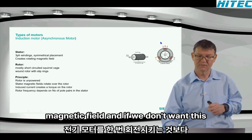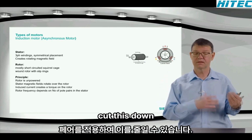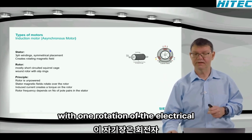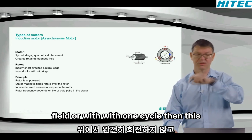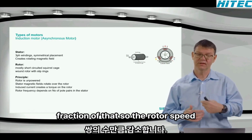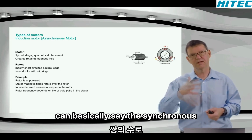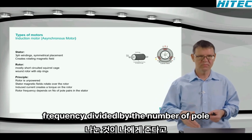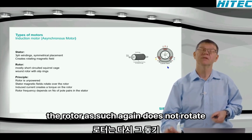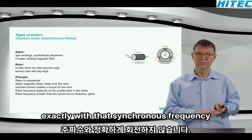And if we don't want this high speed, we can cut this down by applying more pole pairs. Then with one cycle of the electrical field, this magnetic field does not rotate completely over the rotor, but only a fraction of that. So the rotor speed decreases by the number of pole pairs. We can basically say the synchronous frequency divided by the number of pole pairs gives me the frequency of the rotating magnetic field. The rotor as such, again, does not rotate exactly with that synchronous frequency.